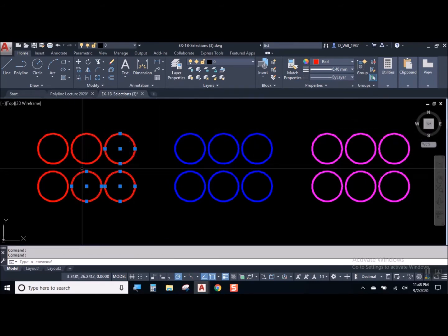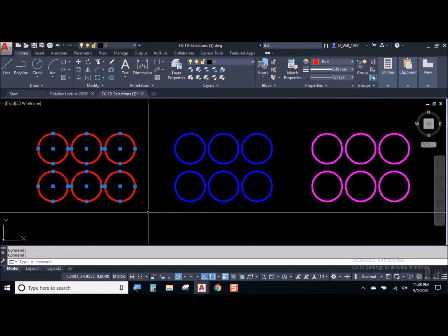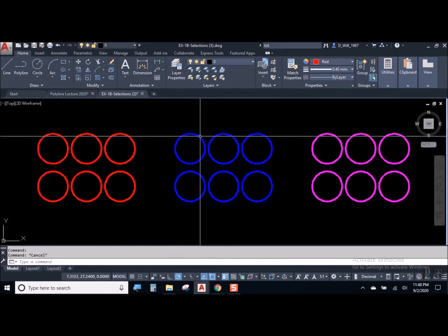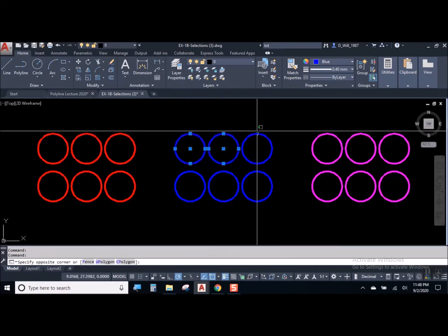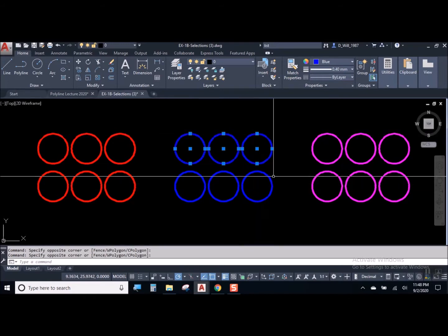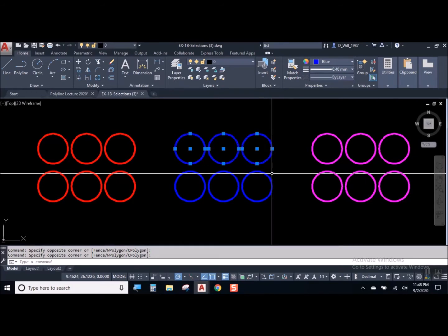So just to review what we've discussed up to this point, you can pick objects by directly clicking on them. That's a pick selection. Now, of course, if you have 10,000 objects, picking on them one at a time would probably be the slowest way to get your job done, right? But that is a valid method for selecting. Generally, you have to click on the lines of the drawing entities. Clicking inside the entity or next to the entity is not going to produce any kind of selection.